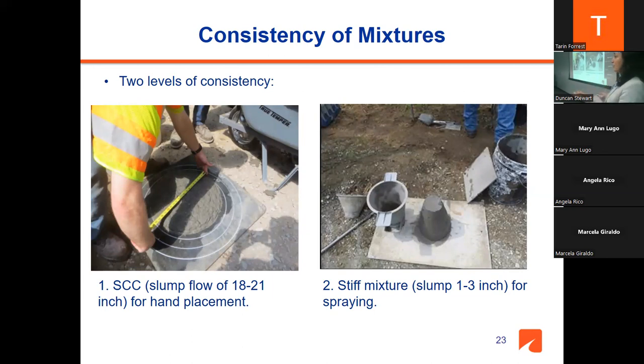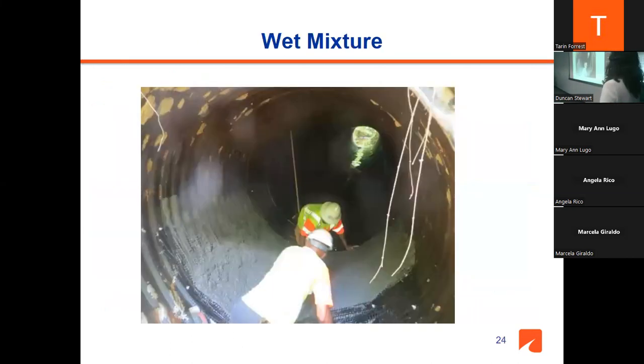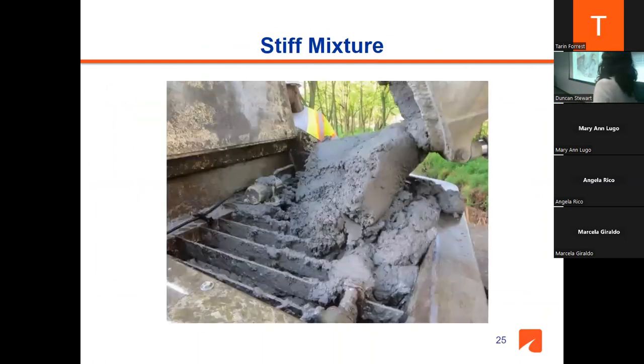Actually, the pump operators asked us for a stiffer mixture. It's easier to disperse the fibers and also easier to spray the ECC. The problem with the wet mixture is that the concrete, as you can see, has some clumps and was sliding down the sides, so it's better to have a stiff mixture. And when we have a stiff mixture, we have to have some vibrator that helps the concrete come down to the grades.